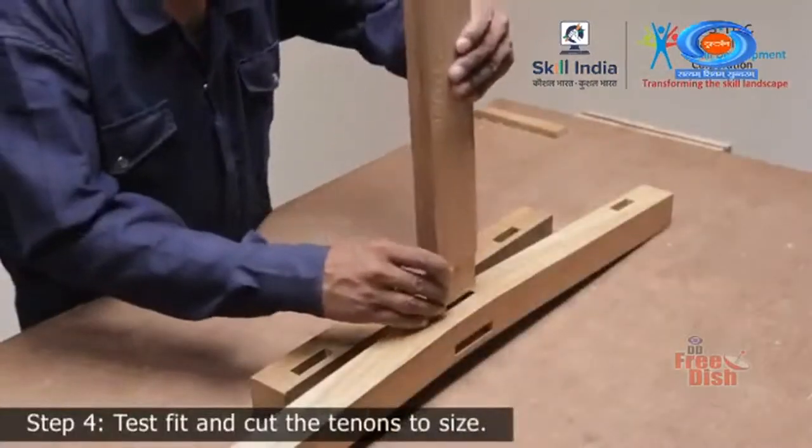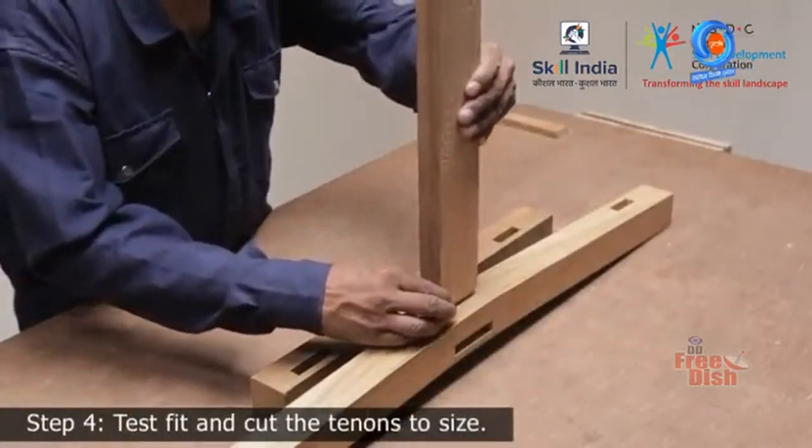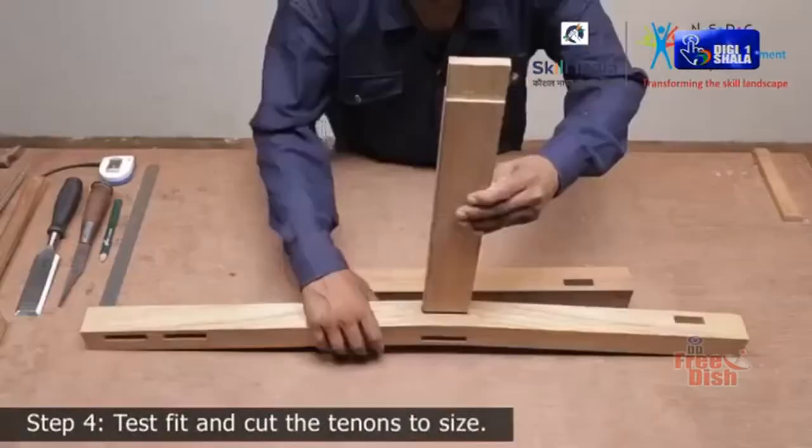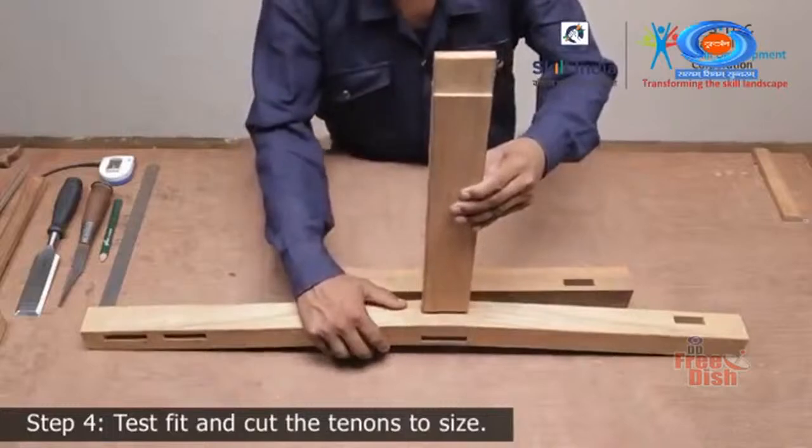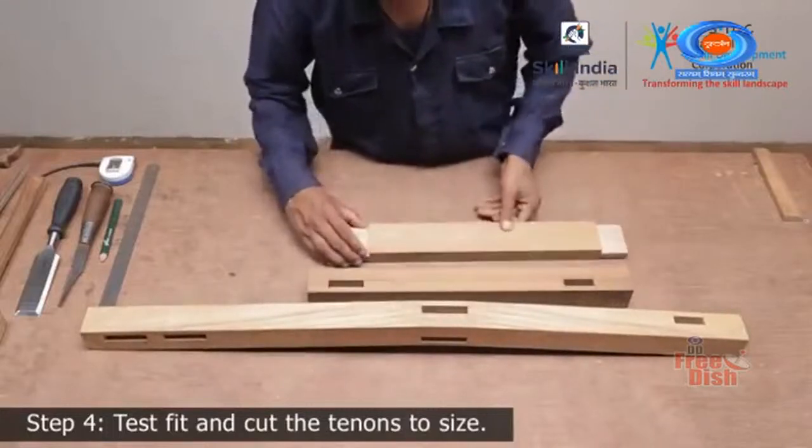Test fit the tenon and the mortise joints in all the wood pieces to ensure that you have a perfect fit. If required, cut the tenons to size as needed.